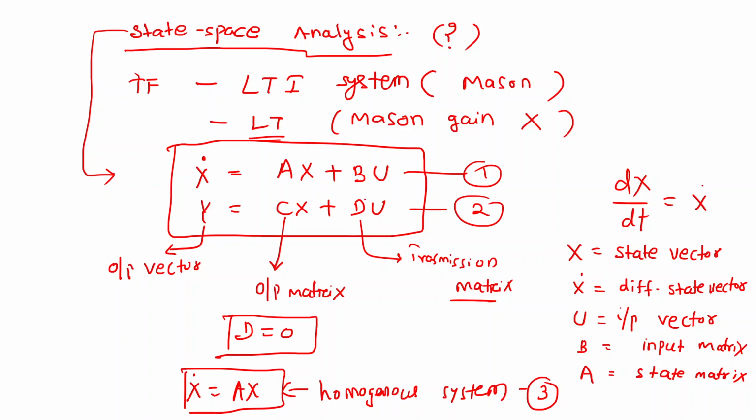Okay, these are all state variables. Generally, the number of state variables in any system is represented by the highest degree. Suppose a differential equation is there, then the highest degree gives the number of state variables. The number of state variables is defined by the highest degree in a differential equation, or this is nothing but the sum of the capacitors plus inductors in the system. Remember that, because these are the energy storing elements and they contribute to the differential equation order.